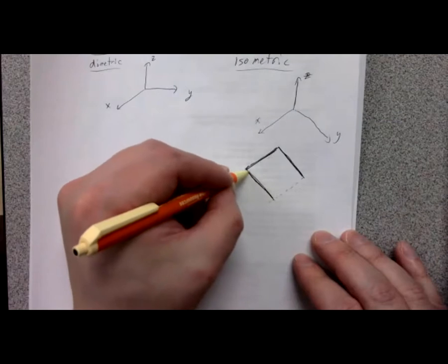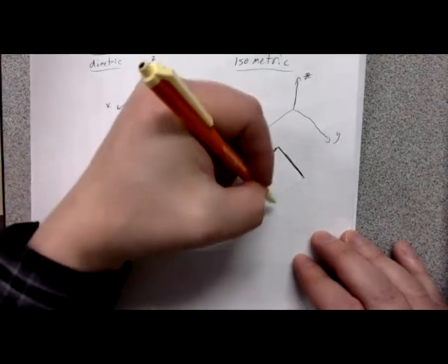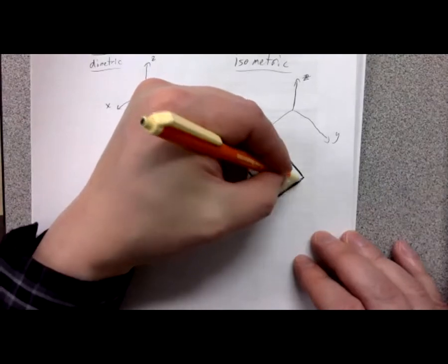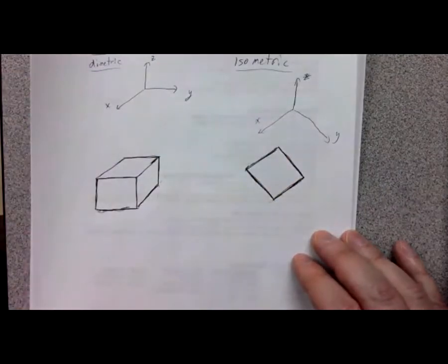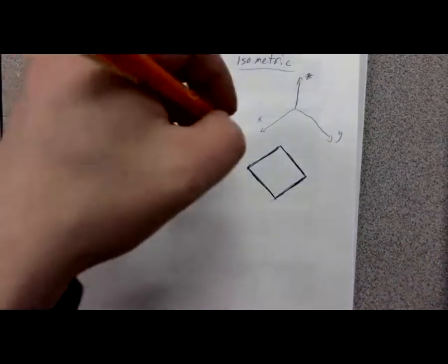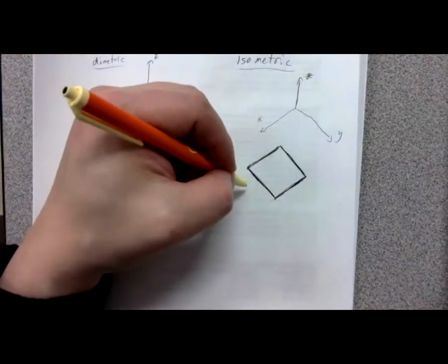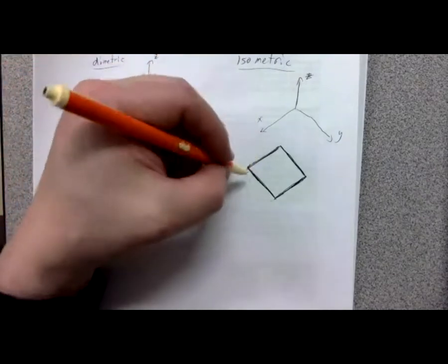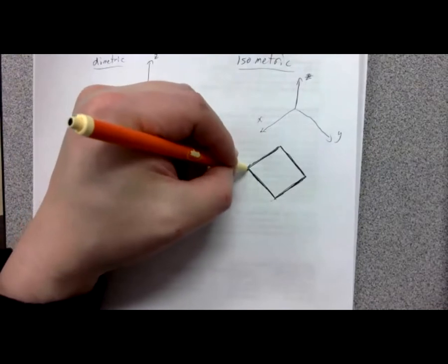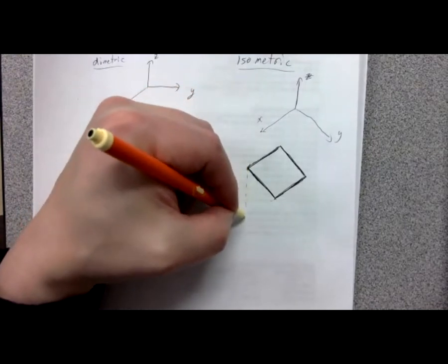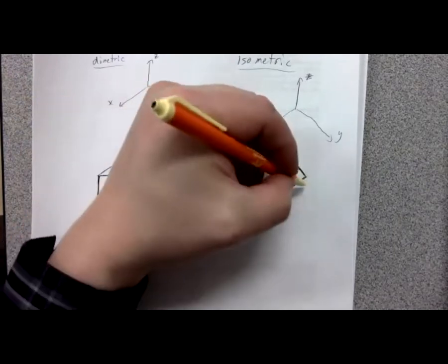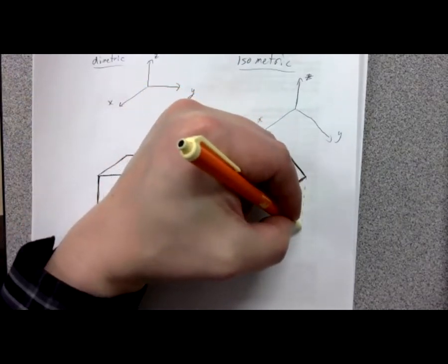Sometimes that method works pretty well: extend from one starting point of a line, extend it out in the direction that line goes, and then using the other parts of the part, figure out where that line should end. That's a fairly common method you can use. It's not the only one. It's not going to work every time. But for a simple object like this, it's not bad. Same thing, I don't know where these corners are down here. So from each of these corners, I can dot lines straight down. That will help me figure out where those points are going to intersect.